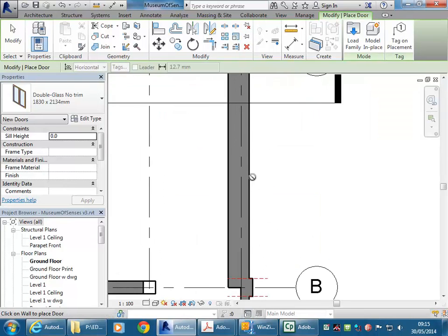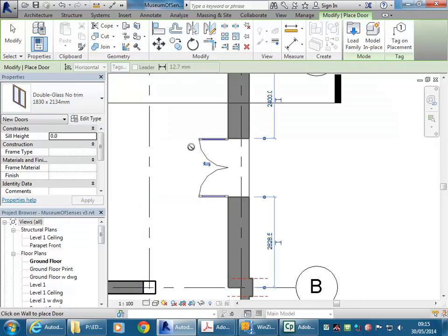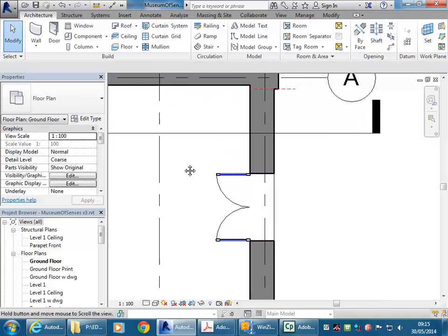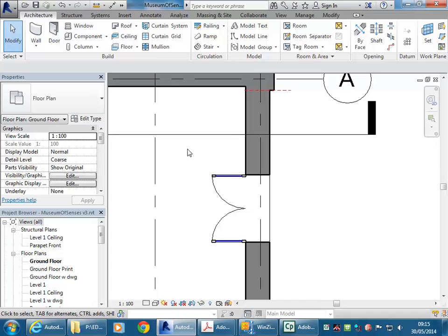and there we are. So normally it will come up selected when you first load something in, and so there we are. I can see I can place the door, so that's working. I'll let you work out the size from the drawings, and then to put the transom above it, you can just use a fixed window and place it above that.